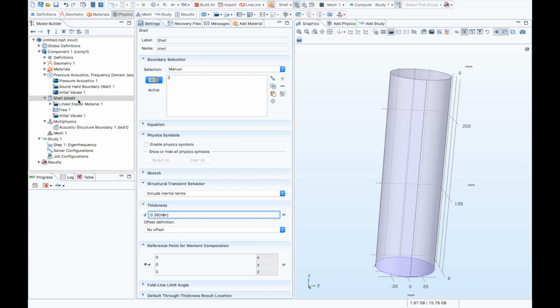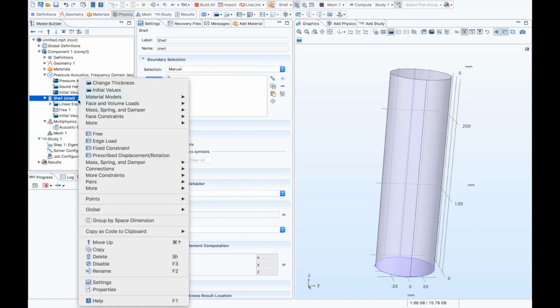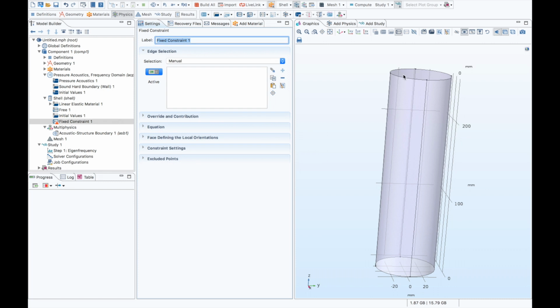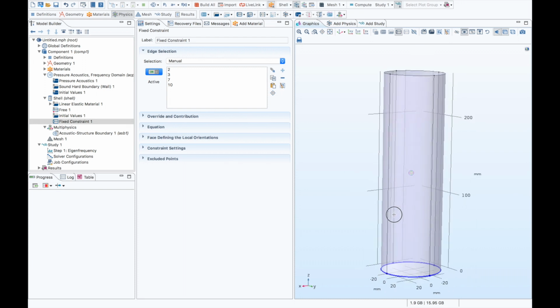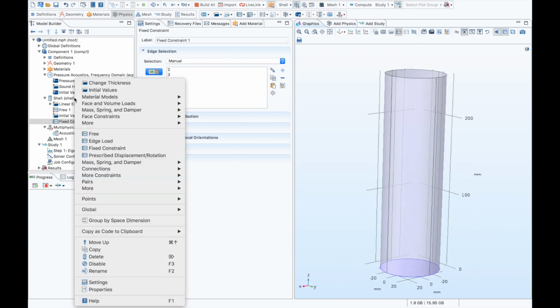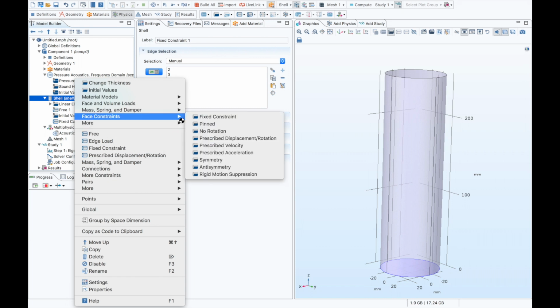Okay, and if we want we can add some boundary condition. So we can set up and solve for the stationary solver or for eigenfrequency solver, or we can set up frequency domain solvers. In this case, if you have some radiation, some vibrating domains, you can add a body load or a rotating frame whatsoever, or you can add a prescribed velocity or acceleration. So if you have some velocity profile or acceleration profile,